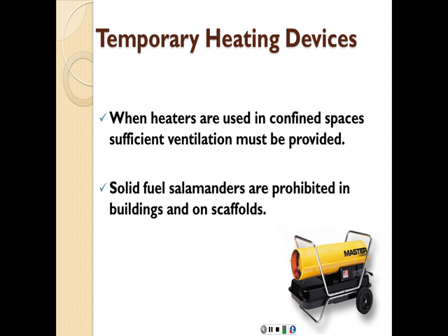When heaters are used in confined spaces, sufficient ventilation must be provided, again because of these fumes and gases. If you're going to use solid fuel salamanders, they are prohibited in buildings and on scaffolds. This is an example of a solid fuel salamander. These are not allowed inside buildings or on scaffolds.